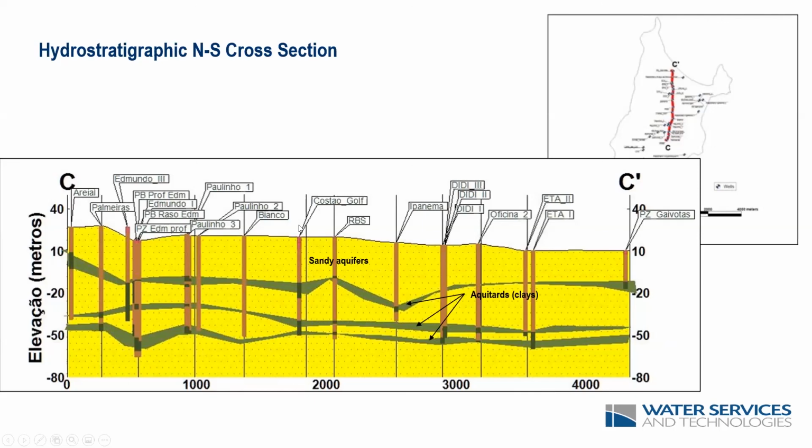So the comparison with the analytical methods, even though there are methods to interpret pumping tests with observation wells in different layers, such as a method called Hantush and Maas, they do not allow for pumping tests which abstract water from more than one aquifer. So this is an example of a more complex situation where you would be limited by using the analytical solutions. So what we did in this case, we did start with the analytical solutions, but then we moved to something a little bit more sophisticated,